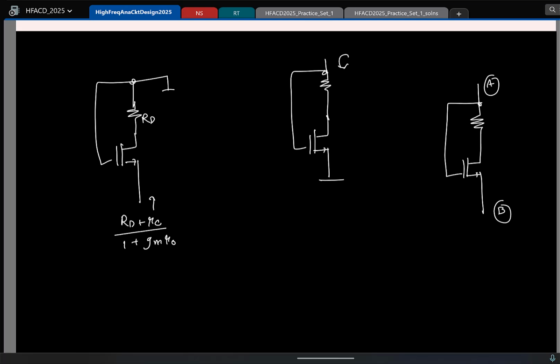One port network. If I have a one port network, to characterize this linear one port network, how many parameters will I need? One. Remember, if it was a two port network, you would need basically 4 parameters. If it's a one port network, I'll just apply a voltage and find what the current is. So I have only one parameter, essentially the resistance or the admittance. So this is now a two terminal device, which means I can model it using a series impedance Z. That's it.